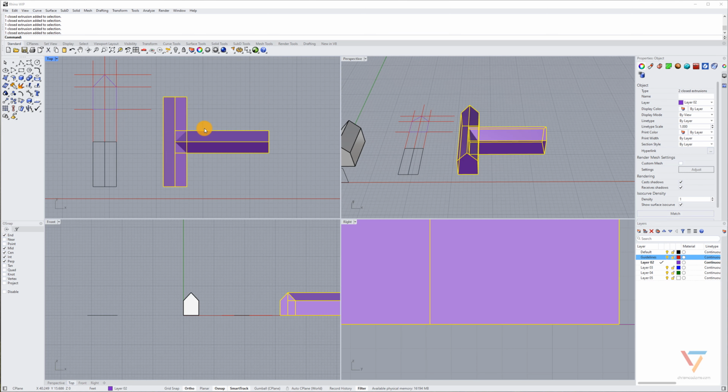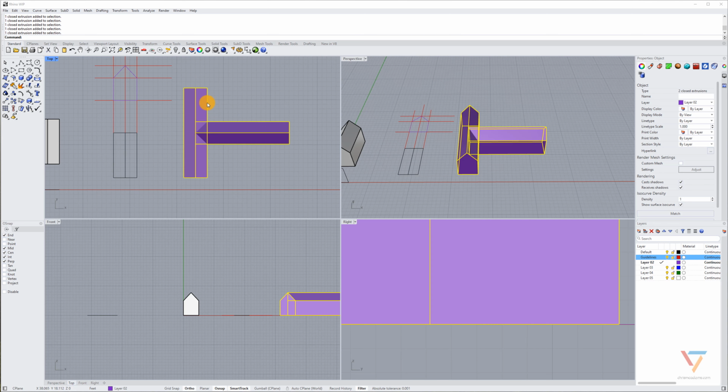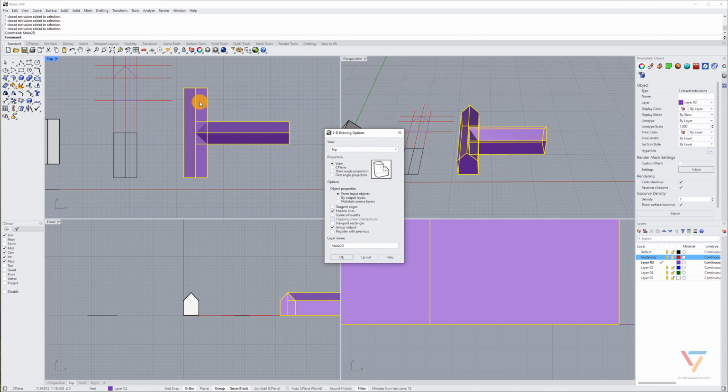Rhino has the ability to make two-dimensional drawings from 3D objects. So let's start here in our top view, and I'll use the command make 2D, and I will generate a top view from our input objects, and we're going to generate both hidden lines and group everything. We will get into a greater level of detail in a future tutorial that looks at the Make 2D options, but in this explanation of what drafting and drawing can be in Rhino, I want